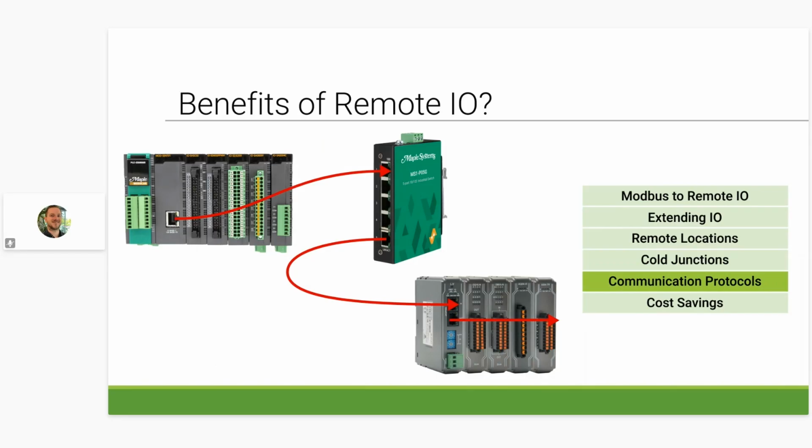Remote I/O offers several different communication protocol options, which make them very versatile in implementing into an already existing application. For example, if your entire facility communicates via Ethernet IP protocol, then you may not want to add a remote I/O that communicates via Modbus. Instead, you may want to pick one that supports Ethernet IP. Here are the communication protocols that our remote I/O modules have to offer and some of the most common PLCs that would use said communication protocols.